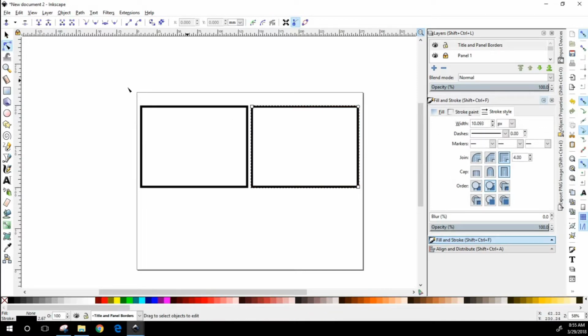See it. So one of the things that's nice and kind of a pain about Inkscape and stroke is when you're scaling objects, the stroke will scale with it. So as you scale an object down, the stroke will get smaller. So if you have a highly detailed character or something and you scale it down, that stroke will scale also, so your detail remains proportional to your image. So sometimes you'll get variances if you do minor scaling and stuff like that to make objects fit. Your scaling might adjust, and sometimes you'll want to return that to its original width, or maybe you just like the scale. So we're going to go ahead and just leave it for now because we're just building a template, and I think it still looks pretty good.